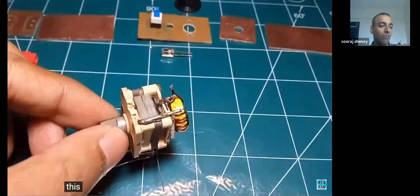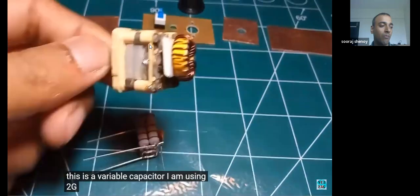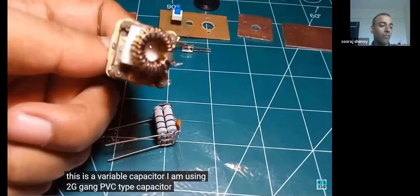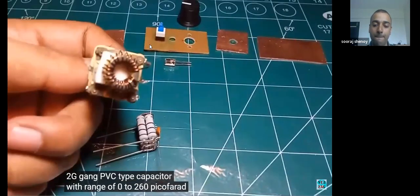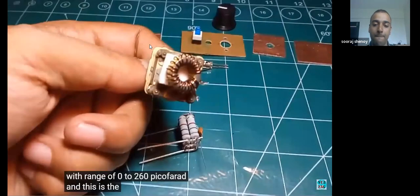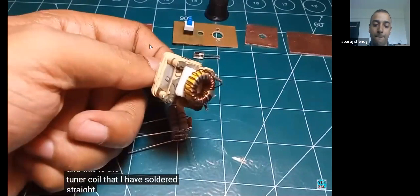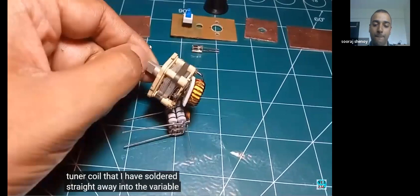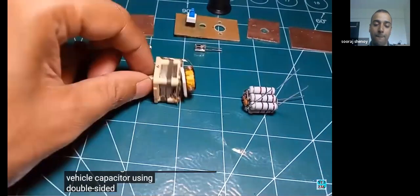And this is the variable capacitor I am using. It's a 2J PVC type capacitor with a range of 0 to 260 picofarad. And this is the tuner coil that I have soldered straight into the variable capacitor and glued on the back side of the variable capacitor using double-sided tape.